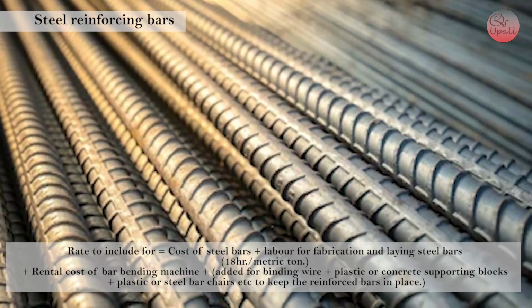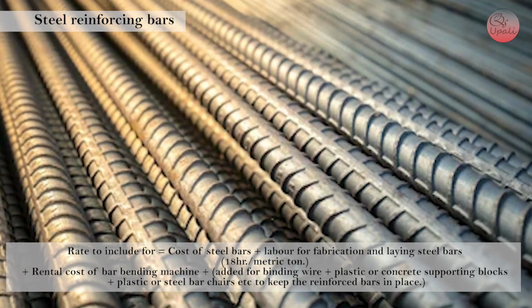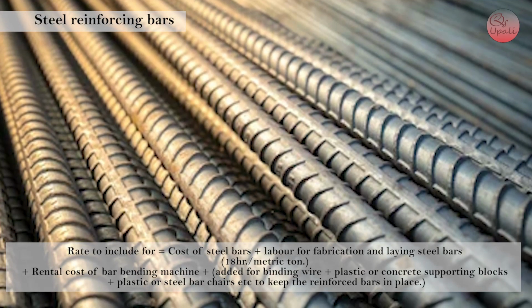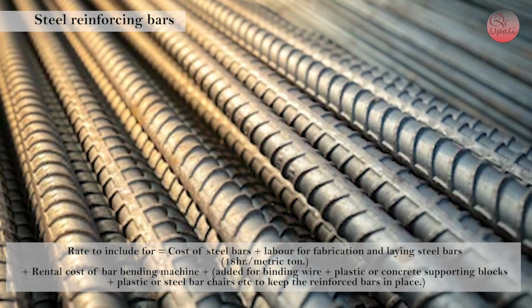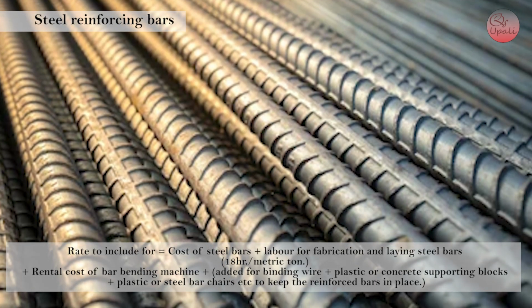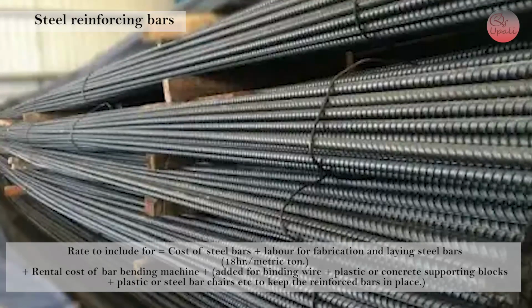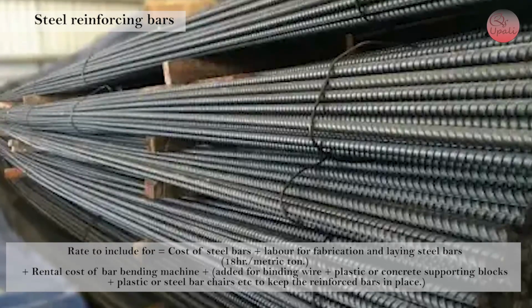Steel reinforcing bars. Rate to include: cost of steel bars, plus labor for fabrication and laying steel bars at 18 hours per metric ton, plus rental cost of bar bending machine, plus binding wires, plus plastic or concrete supporting blocks, plus plastic or steel bar chairs etc. to keep the reinforced bars in place.